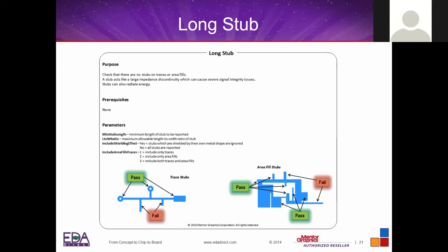You don't do that nowadays on fast edges. So it's not about frequency, it's about the fast edge. You may have a 10 megahertz signal, but if it's running with a really fast edge rate, it can be more problematic than a 300 megahertz signal, which has a slower slew rate. Okay. And these stubs actually can hurt you.